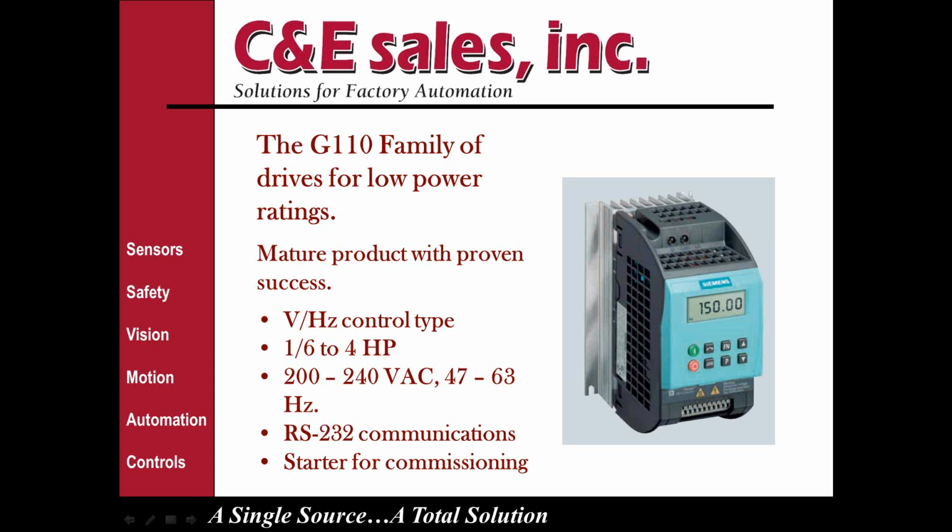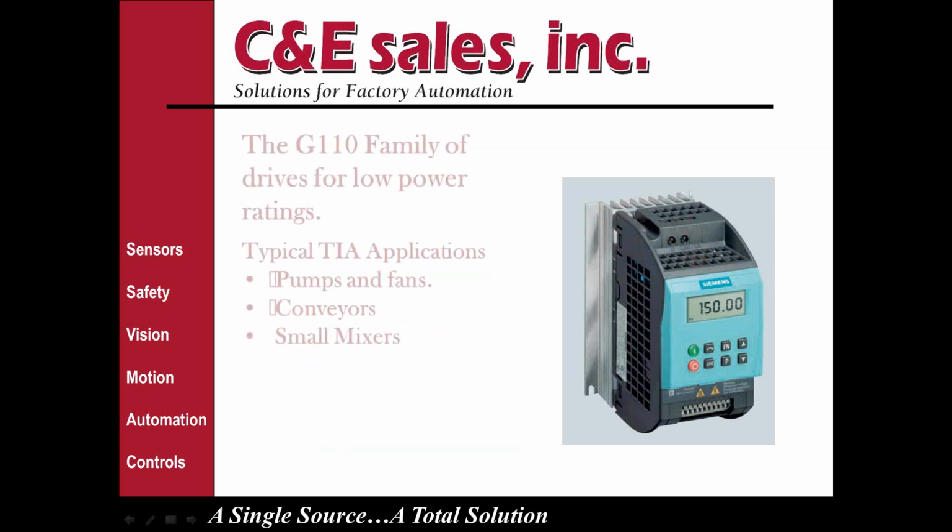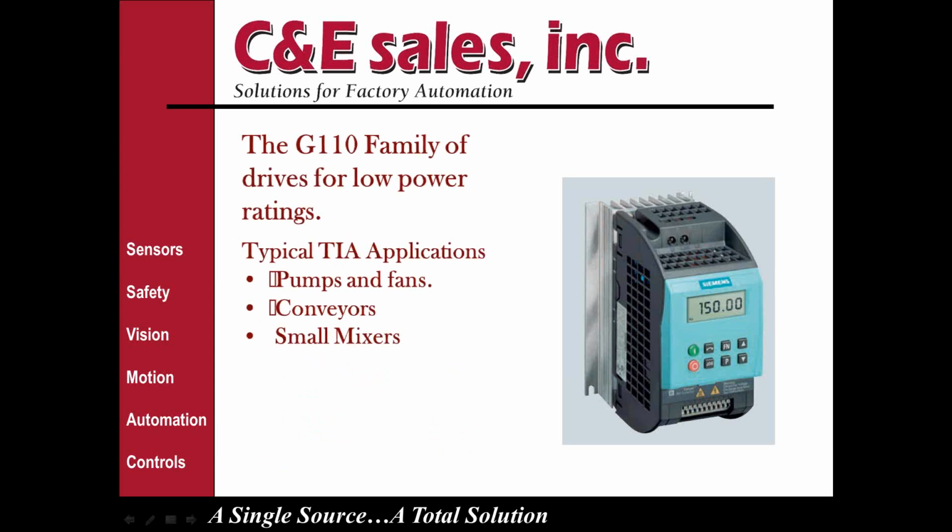Like the V20, it has the RS-232 communications, Modbus RTU, but it does have Starter for commissioning, which is a very handy feature to have. The drive is similar to the applications from the V20. It's configured for pumps and fans, conveyors, and small mixers.